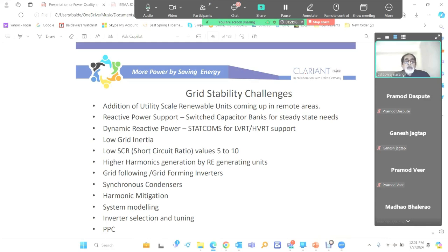So now many tenders are coming with battery backup only. As we go along, we have to see that we are not having a weak grid, and we have the ultimate aim to go 100% renewable. So all these challenges have to be taken care of, and this is why STATCOMs have been taken into account. For grid inertia, either we have to have synchronous condensers in the system, or we have to have battery backup. Then only can this be increased.